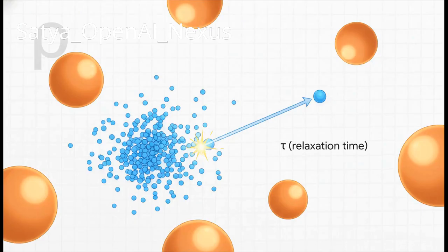Now, I know this formula looks a bit scary, but stick with me because it tells a really simple and beautiful story. It connects the resistivity we can measure in a lab to what's happening with every single electron. All it's saying is that resistivity depends on stuff like the electron's mass and charge, plus two key things about the material. N, which is how many free electrons are packed in there ready to carry current, and tau, which is the average time an electron gets to move before it smacks into an ion. See? The more free electrons you have and the longer they can go without crashing, the lower the resistivity.